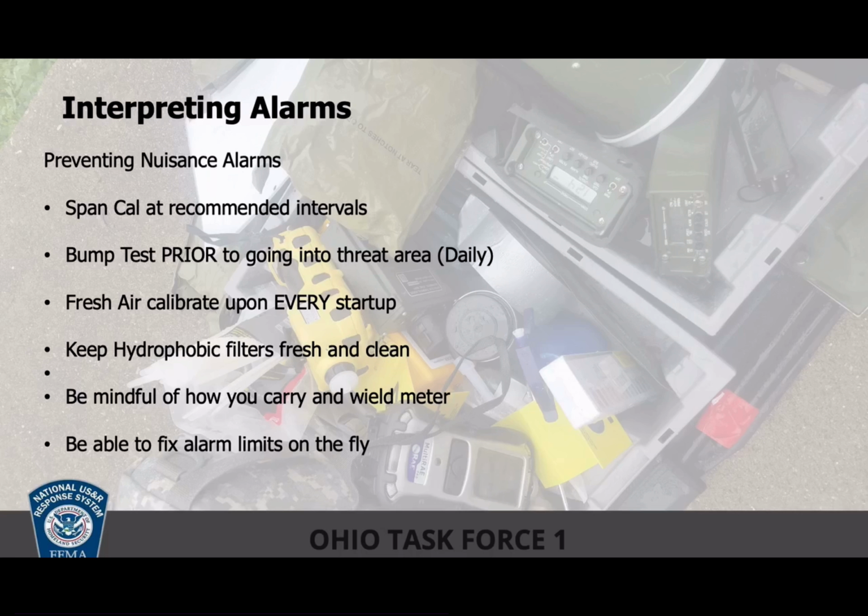Always perform a fresh air calibration every time you start up. When I say fresh air, I mean actual fresh air: not in the bay next to the fire truck after you just turned it off, not outside next to an idling fire truck, not next to an idling generator. It needs to be actual fresh air.